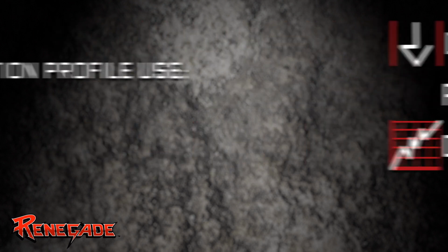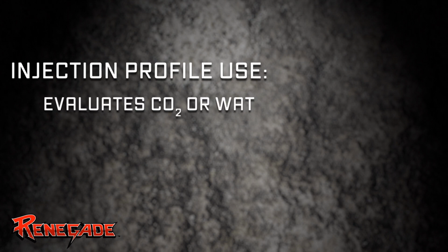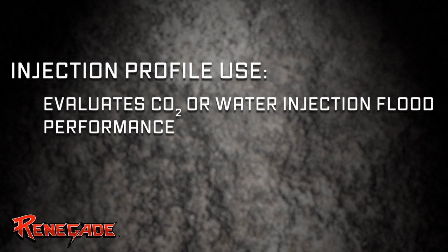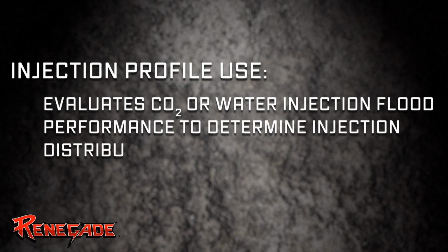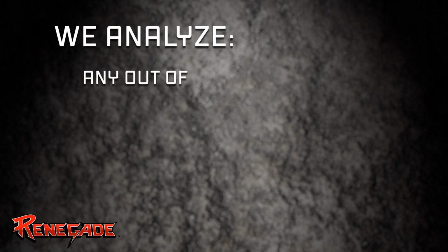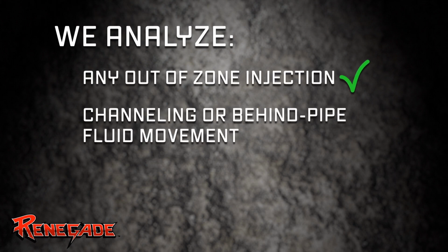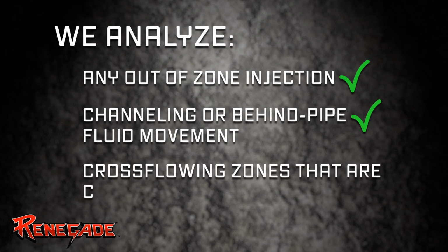Injection profiles serve our customers in a variety of ways. The most common is to evaluate CO2 or water injection flood performance to determine injection distribution as it leaves the well. We analyze any out-of-zone injection, channeling or behind-pipe fluid movement, and cross-flowing zones that are communicating.